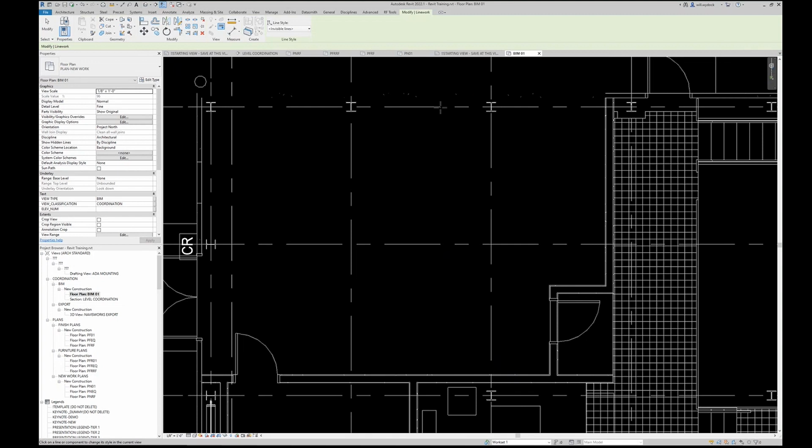But these type of line work features can be overridden for other parts. This order of operations in the software can impact how you work and what you can do with them, and why certain things don't work, why object style doesn't work because of the duct and pipe systems, and so on, things like that. So it seemed like I was jumping all over the place with what I was talking about in that first part. We're going to build upon that, and we're just going to build it in different areas. So one of the first things we're going to talk about is part of the graphics for the view and settings specific to it.